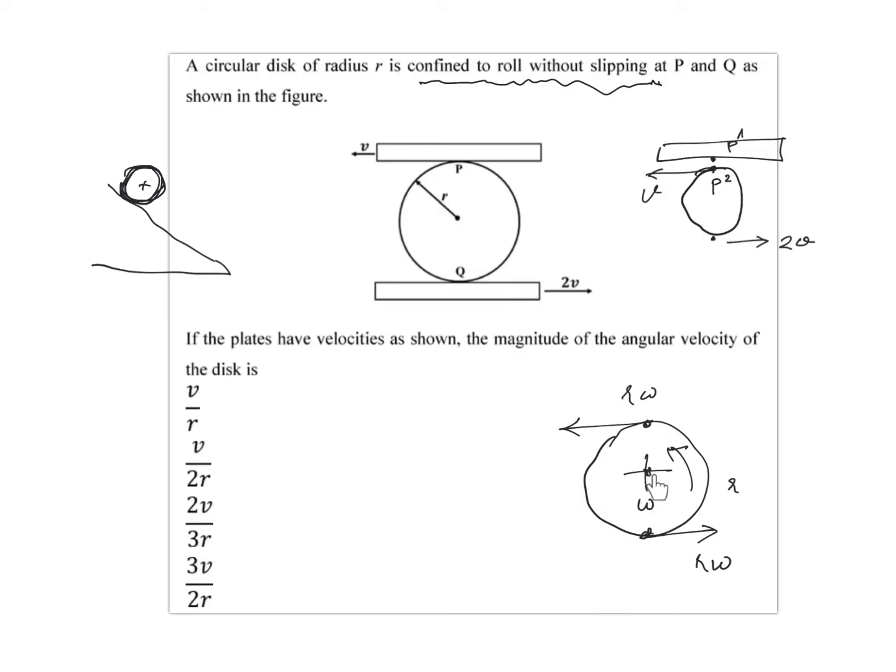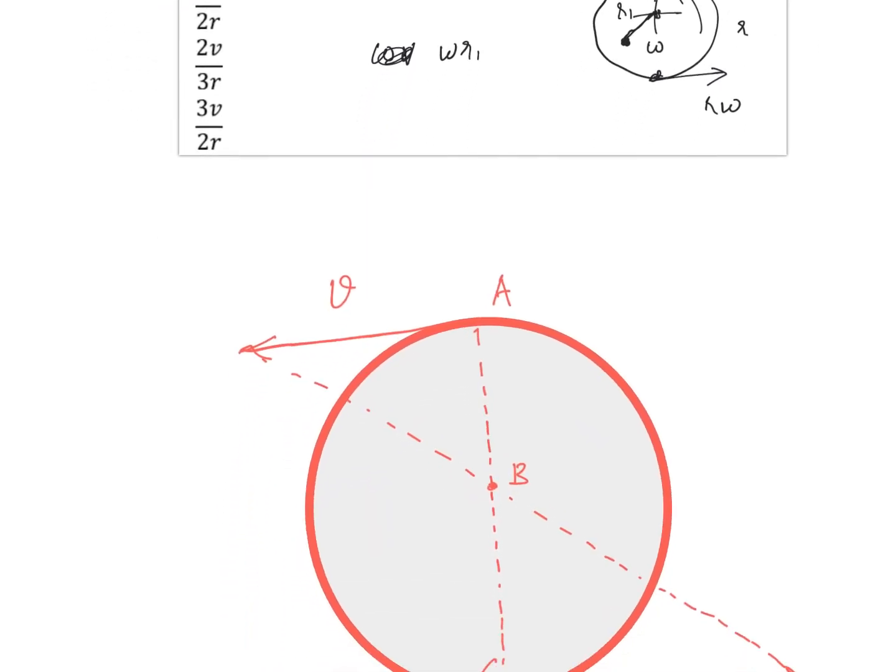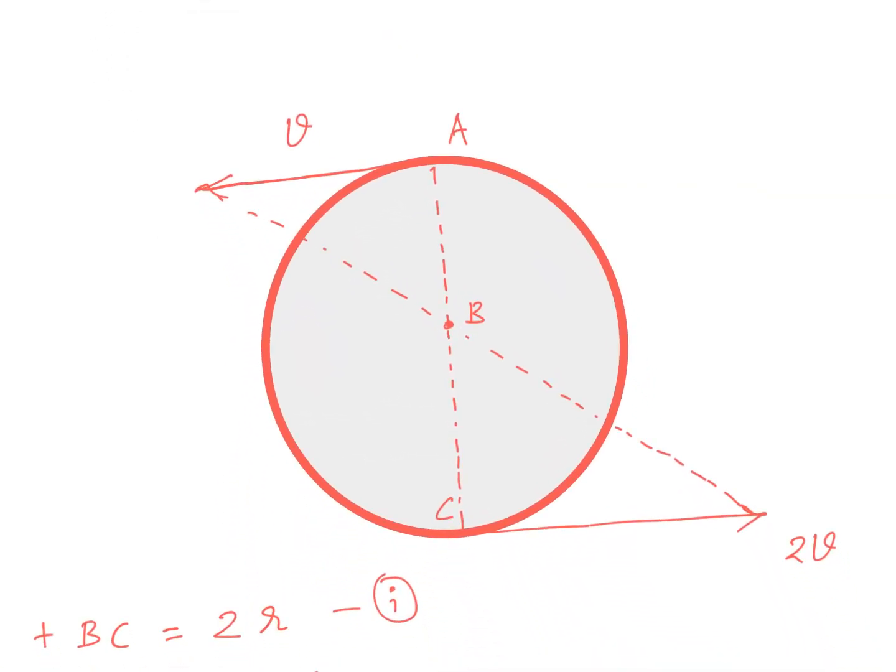If you know the axis, the velocity at any point that arises out of pure rotation can be evaluated as omega times the distance. If I am interested in calculating the velocity of this point, and it is at r1 distance from the center, then the velocity is omega times r1. So it is fairly easy. That's the motivation for why we find instantaneous centers. Makes sense?